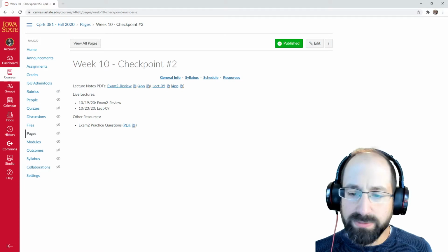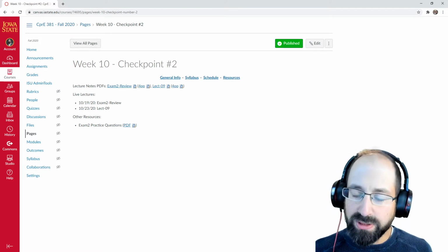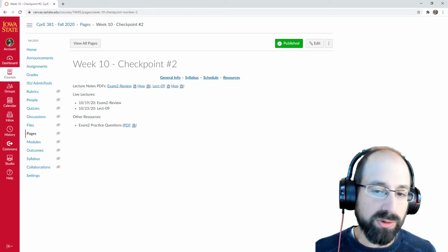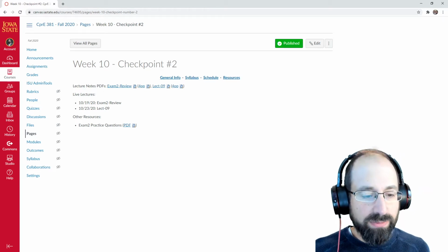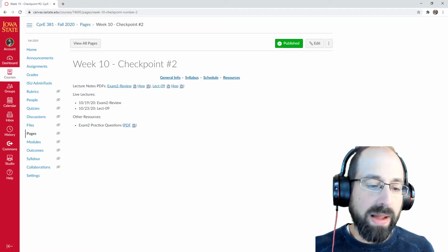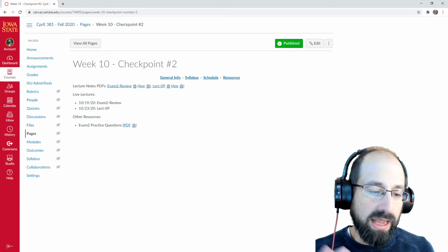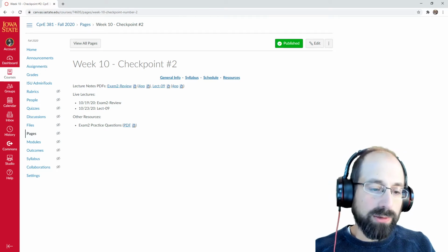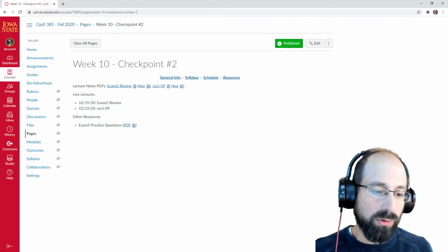There was a question about Project B, something about the byte addressability of the register file, but the register file is just that word addressable component. There is still that same issue where MIPS for the data memory assumes a byte addressable data memory, and our memory module that we just provided for you is a word addressable memory, and you do need to be aware of that.